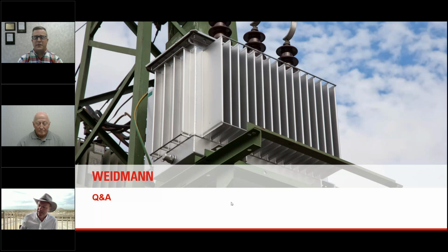I can maybe answer that one. So yes, the answer is that the hot spot of these kinds of layer wound transformers is seen by and affects the layer insulation paper specifically. And so the other materials, for example, the duct strip cooling sticks, are not necessarily in the hot spot. Therefore, typically duct strip does not have to be a special material. So a hybrid solution where DPE is the layer insulation, but with standard duct strip and even standard pressboard components, for example, insulating the coil from the core, that hybrid system can still have these extended thermal classes.